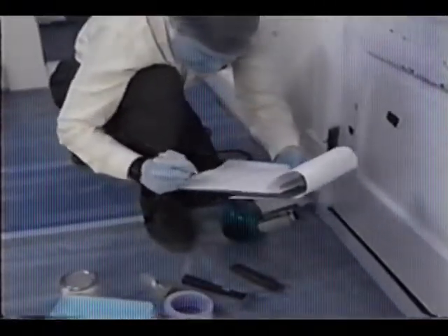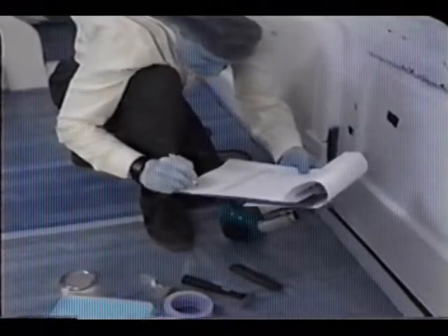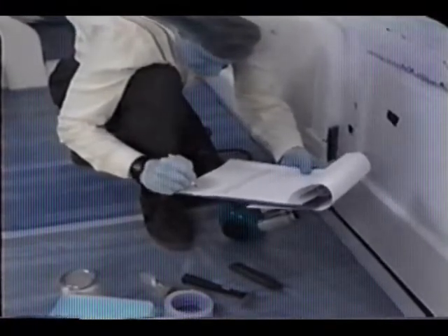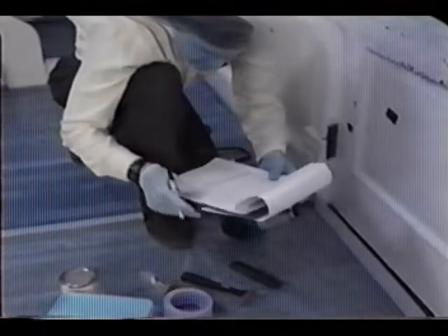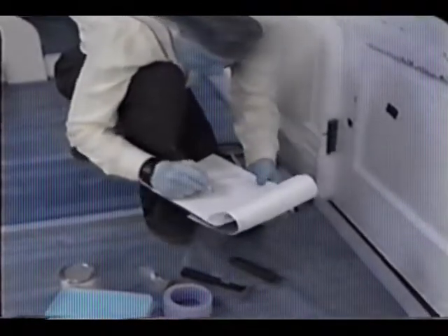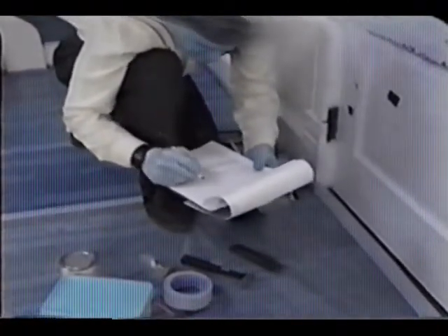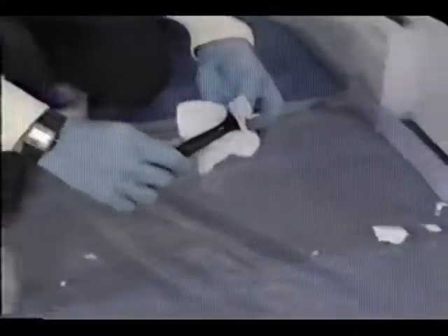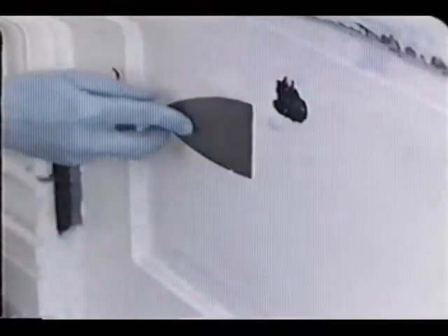For samples that were measured exactly, record the dimensions and area of the sample in centimeters. Once the sample is in its container and the paperwork is done, you can clean up the containment and repair the surface. Use disposable wipes to clean up tools and dust, and place these in the trash bag. If the owner requests, repair the surface with spackling and/or new paint.